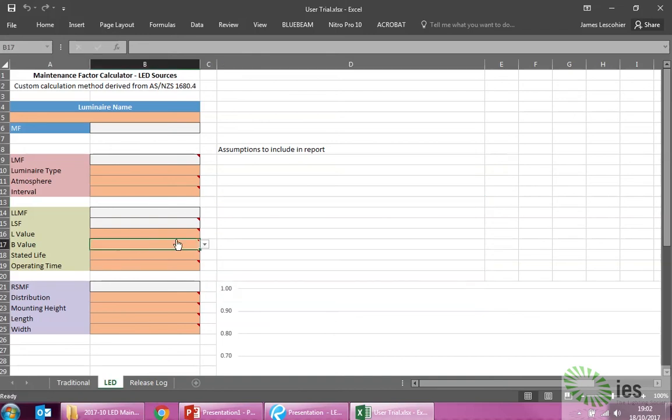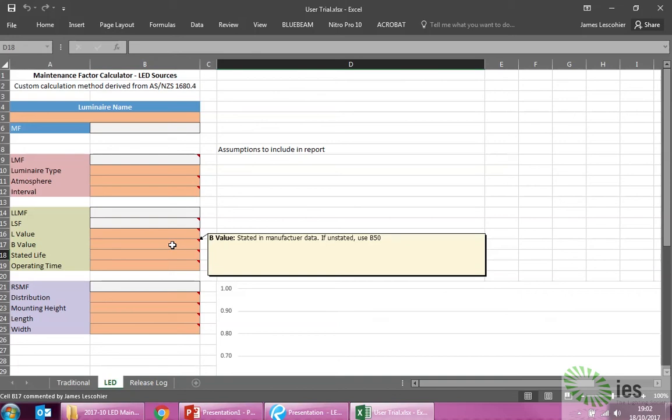Yes. You're using that as a B10 luminaire, meaning that 10% of those luminaires have got down to that L90 or L70 value. Whereas for a lot of manufacturers, the B value is a survival factor. So B10 of 100,000 hours means that 10% of those luminaires have failed, as in less than that value. Less than that value. Okay. That is what they mean by it.